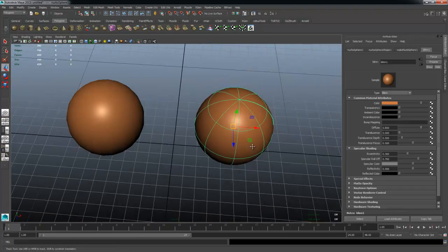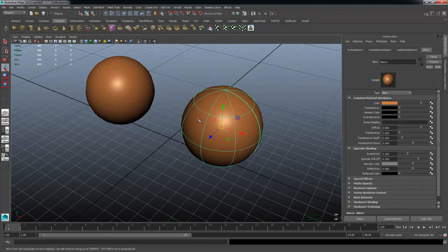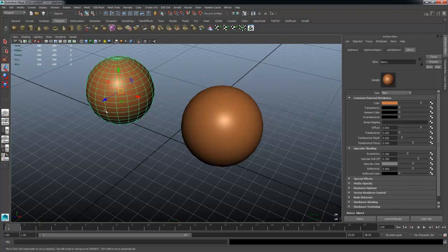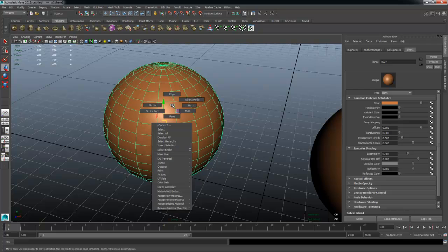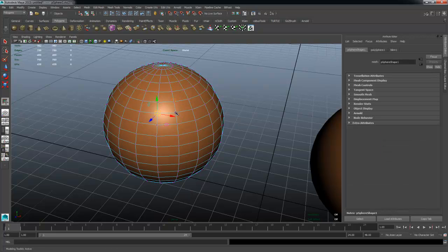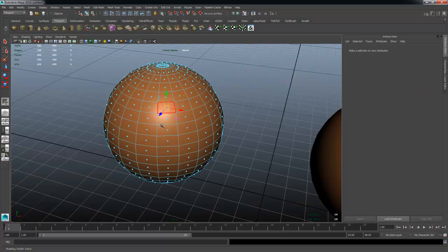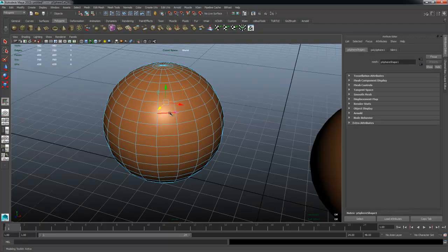Essentially, the one has the ability to calculate the surface based on an algorithm, calculating it mathematically and then trying to cut the shapes accordingly, whereas this one on this side is purely based on the 3 or 4 component type that makes essentially one polygon. On the one side we have edges, vertices and faces. If you right click on your model, you'll see you have edges, vertices and faces. So these guys are your vertices, here's your face, and finally the edges.